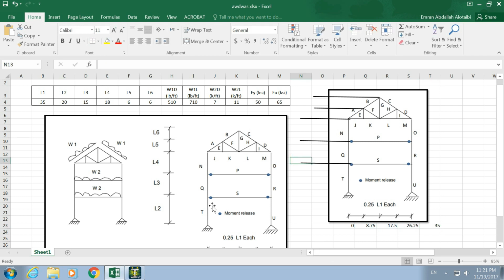And for the y-axis, we know over here it's L2, direct forward. For the other joint, we're going to put L2 plus L3. For the third joint, L2 plus L3 plus L4. For the fourth joint, it is L2 to L5. And for the last one, it is L2 till L6. Now I have my bounds here.